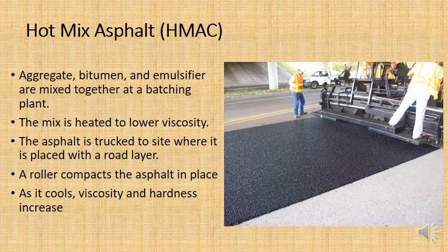This works quite well, because once it cools down, the viscosity of the bitumen will increase, and the hardness of the bitumen will increase, and that will mean that the strength and the durability of the asphalt road surface will increase too. So it's workable while it's hot, and then as it cools, it becomes hard and strong.